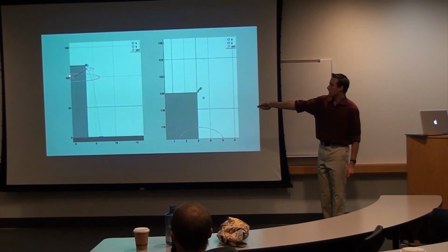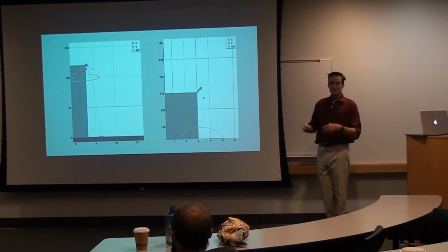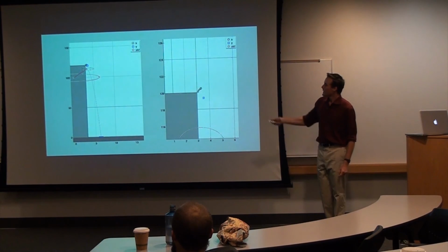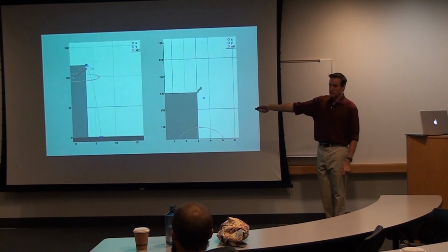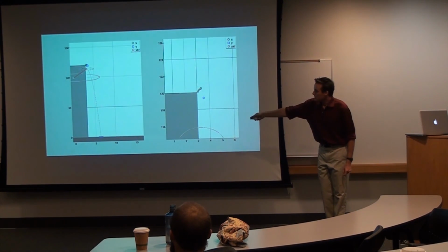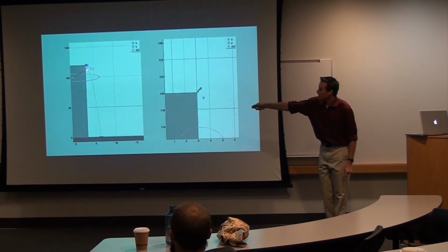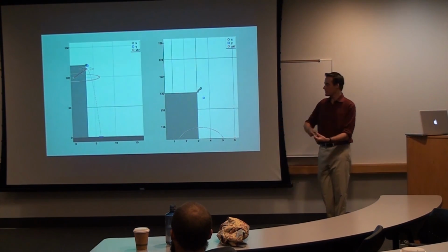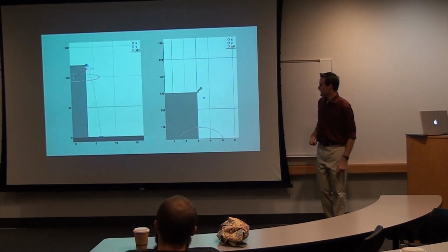And it's not exactly on the line because there's also the velocity, which is also part of the state that you're not seeing here. And the uncertainty in the estimate has now shrunk a little bit because of the information from the measurement. And now you can see the pink line a little bit easier. This is how the guy would go if this were his exact position and velocity. And so this thing here would be the set point of the cushion as it decides where to try to go to catch him.